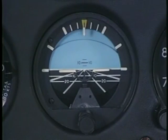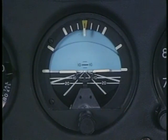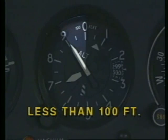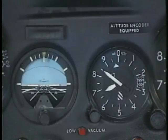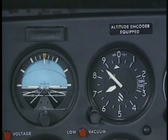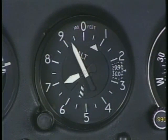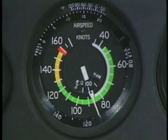When you have determined that a correction is necessary, stop the movement by adjusting the pitch attitude slightly. Then make the necessary adjustments to return to your desired altitude. Normally, if the altitude deviation is less than 100 feet, use a correction of a half bar width. If the deviation is greater than 100 feet, initially use a full bar width. Once the new pitch attitude is established, check the altimeter, vertical speed indicator, and the airspeed indicator to see that you have made the proper correction.